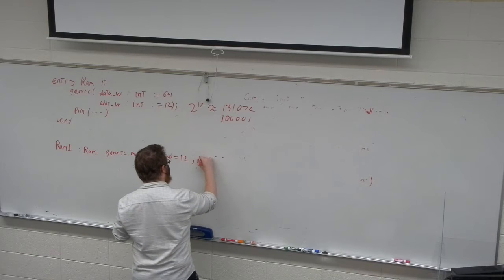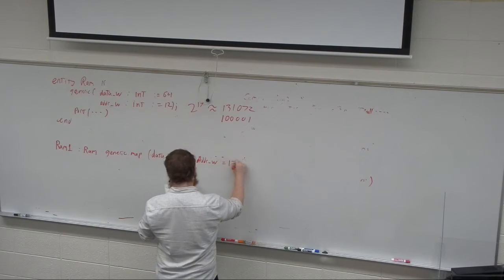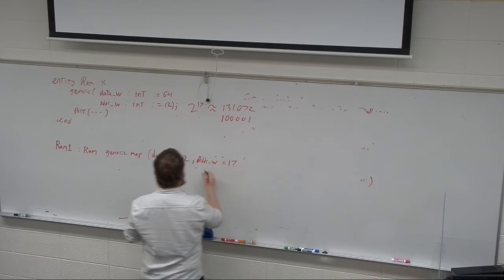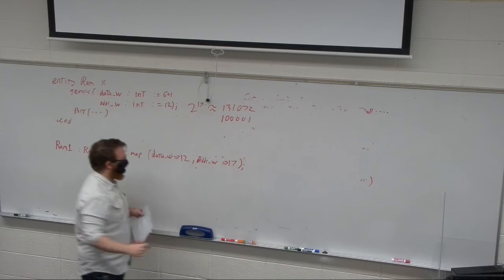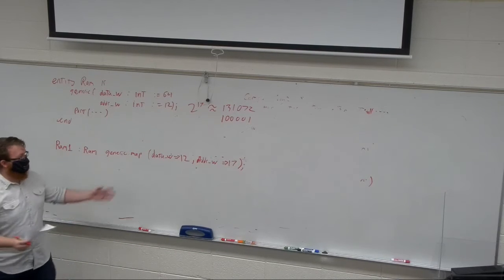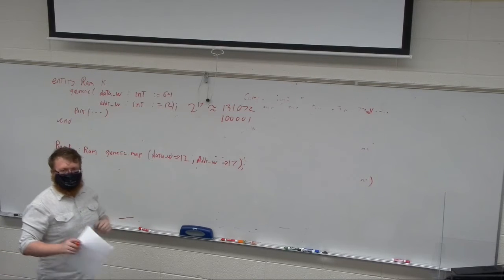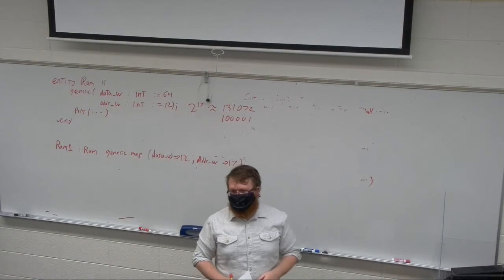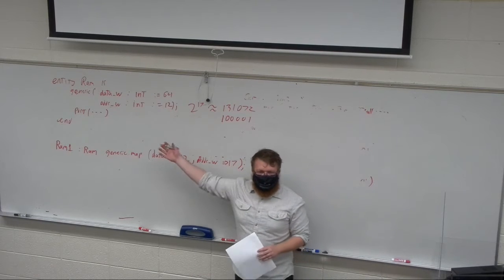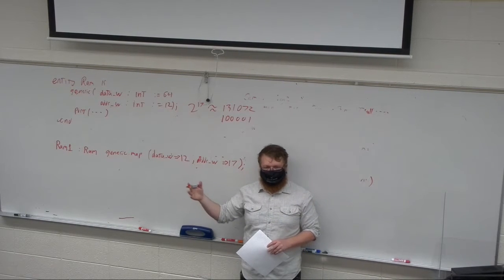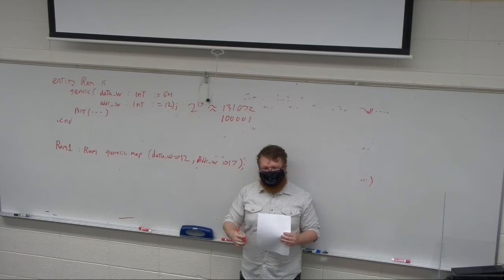And your address width is equal to 17. Now I've created that generic map. When this RAM gets instantiated, it will make my RAM the size I want it to. So that's generics. That's all they really are. It's a way of passing parameters to your components upon instantiation, so each instance can be different.